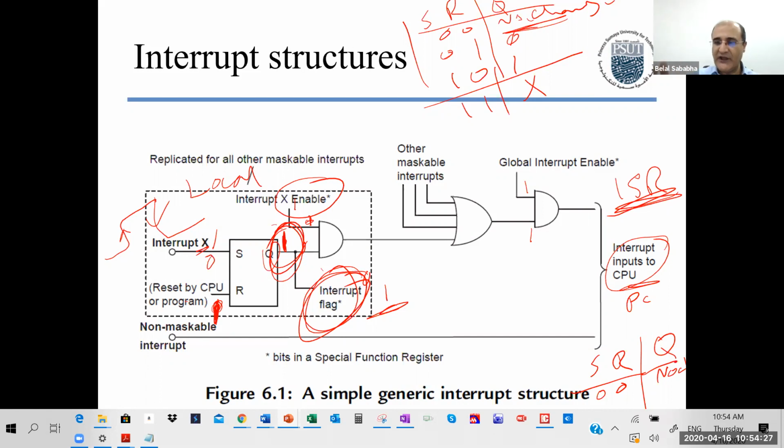Just like when you're in an airplane, for example, and you want service from the helper. You push the button for the waiter, and a light turns on. The waiter will see it and will come and ask you what you want, and will serve you. But the first thing he or she will do is turn off the light, or lower the flag. Otherwise, somebody else sees the light or the flag raised again and keeps doing that. A lot of people write programs and forget to clear the interrupt flag in the interrupt service routine. So their program hangs.